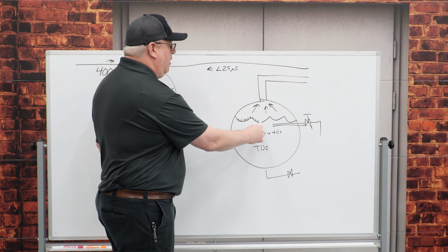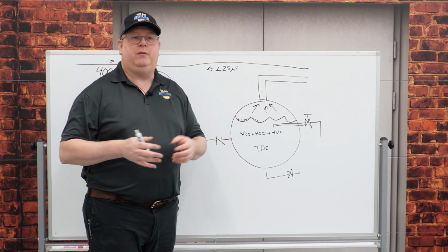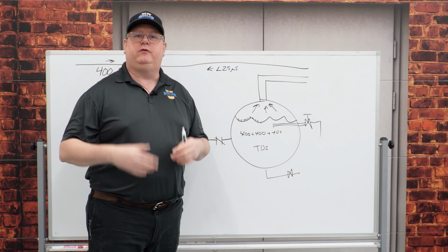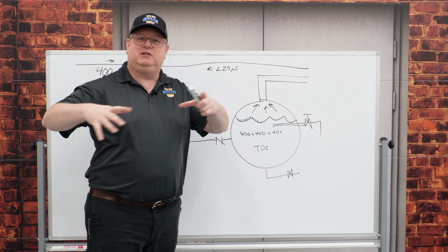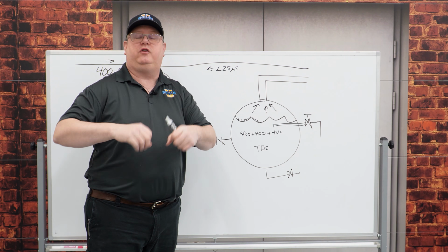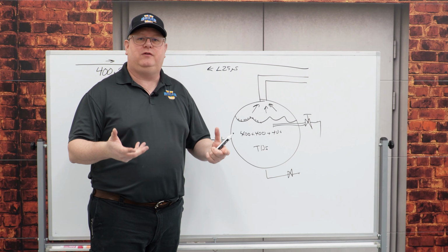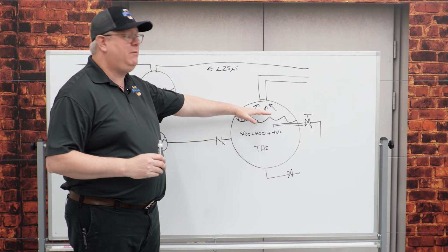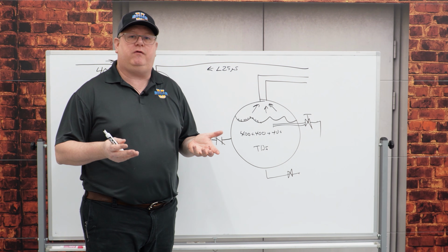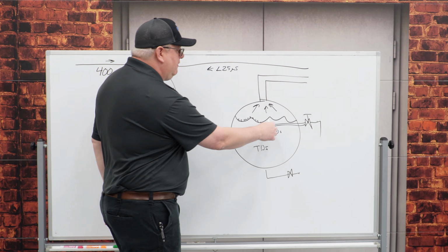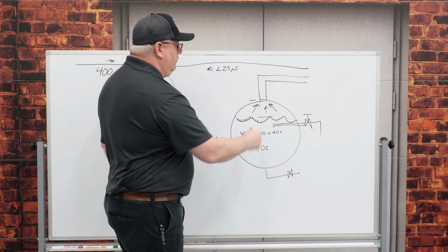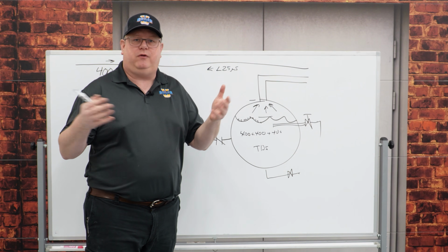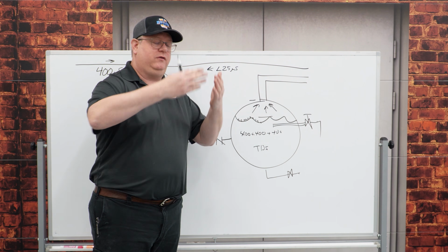If you take a pot of water, freshly filled from the sink, and you boil that on the stove, it doesn't boil over. You throw spaghetti in there, the starches seep into that water, they're dissolved and become dissolved solids. Now the pot foams and spills over. Well, the same thing can happen with a boiler. We call that carryover because there's only a little bit of space for the steam to separate from the bubbles and for the bubbles to pop and burst and the steam to travel out.